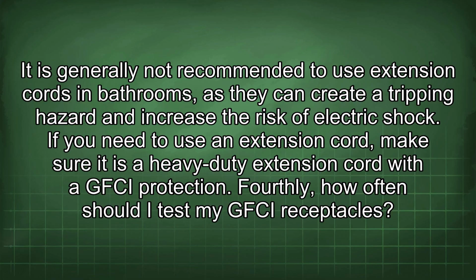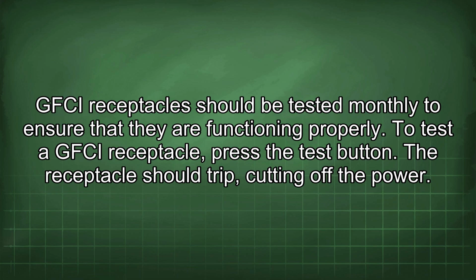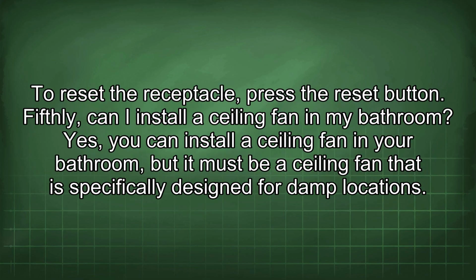If you need to use an extension cord, make sure it is a heavy-duty extension cord with GFCI protection. Fourthly, how often should I test my GFCI receptacles? GFCI receptacles should be tested monthly to ensure that they are functioning properly. To test a GFCI receptacle, press the test button. The receptacle should trip, cutting off the power. To reset the receptacle, press the reset button.